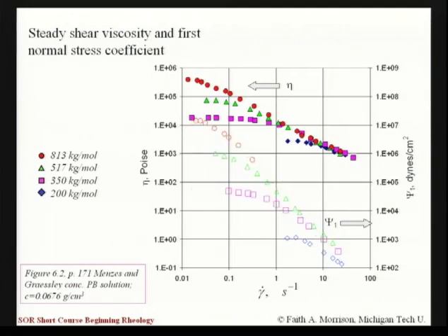So that's the reason. It's a very practical reason. It just looks good. And why does it look good? Because there are many materials for which N1, meaning tau 1, 1 minus tau 2, 2, doesn't approach a constant, but goes like gamma dot squared at low rates. And so if you divide that out, it approaches a constant.